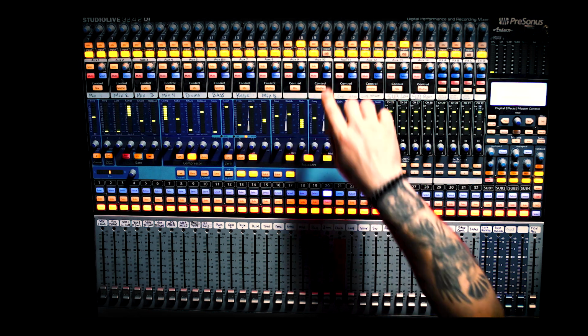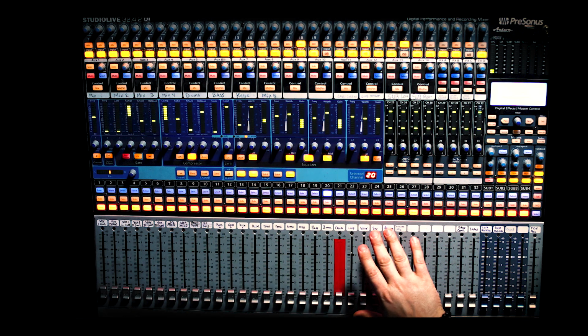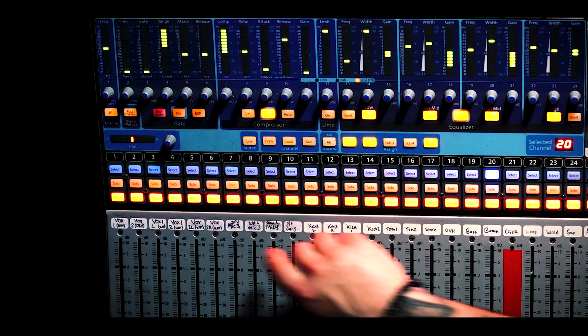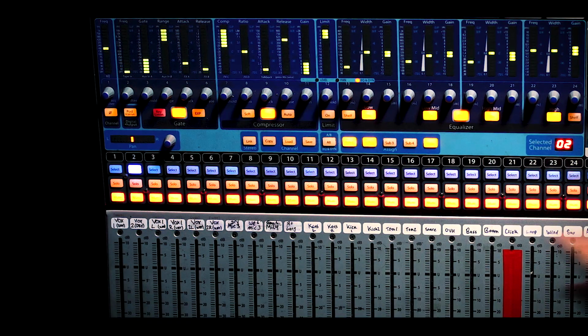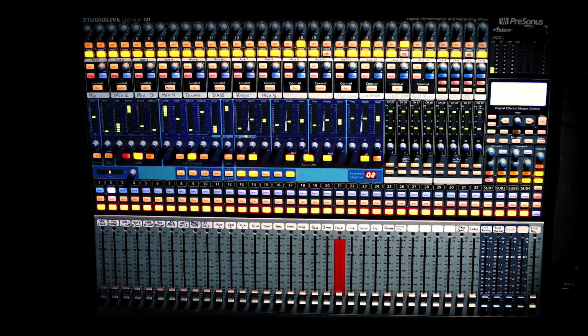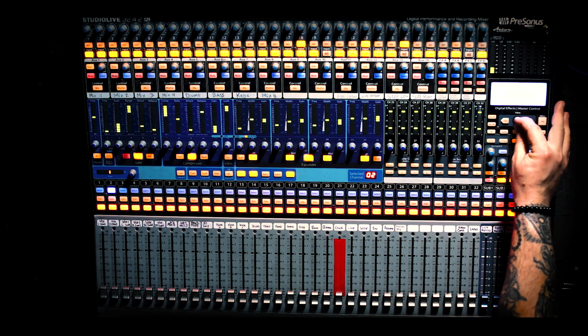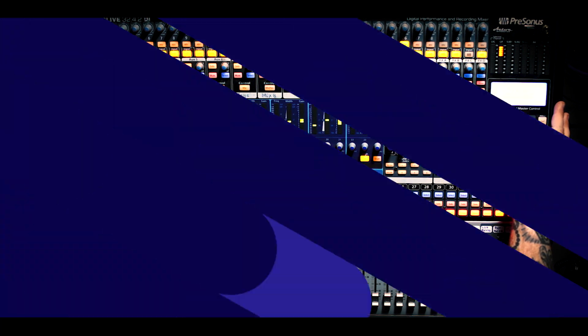However, most of our channels are connected through the digital stage box, so we will remotely adjust the preamp in the stage box. Let's select a channel on the network. Selecting this channel, we will use this encoder pot to trim or gain the decibel strength of the input source. The same goes for all networked channels.